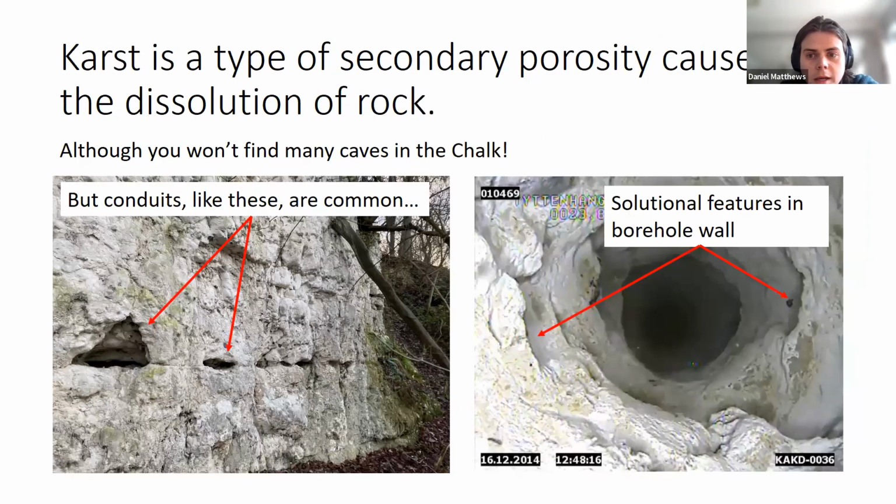Okay, so what kind of features can conduct flow through a body of rock at greater than 5 kilometers a day? Because even through a well-connected chalk fracture network, something like 30 meters a day is considered really fast. So larger voids are required. And these voids formed by dissolution are known as karst. And classic examples of karst landscapes, with large sinkholes and big cave systems characterising them, can be found in areas like the Peak District and South Wales, where the bedrock is the Carboniferous limestone.